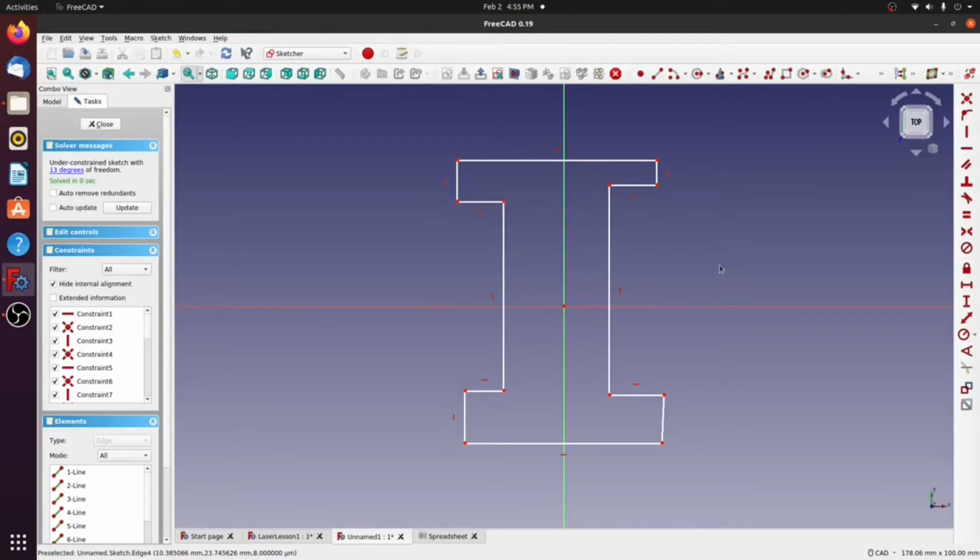There we go. And now you can see that we've got a certain thickness on this tab over here, but it's still unconstrained because I can move it around. And what that means is that if I'm just looking at it, this may look right, but it could actually be a little bit off, and I just can't tell by looking at it here. So we're going to apply another constraint that will ensure that this tab is the exact same thickness as this tab.